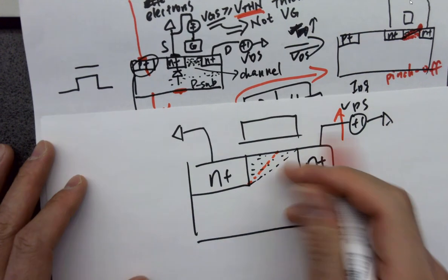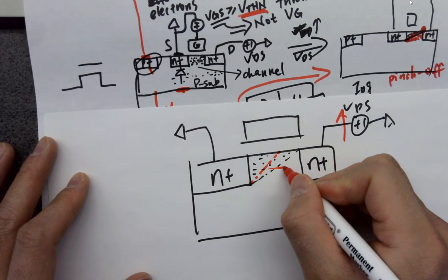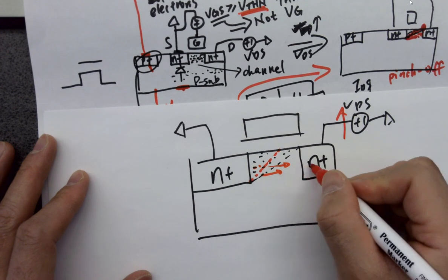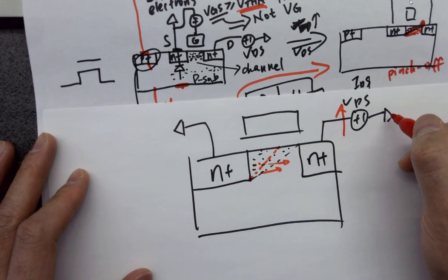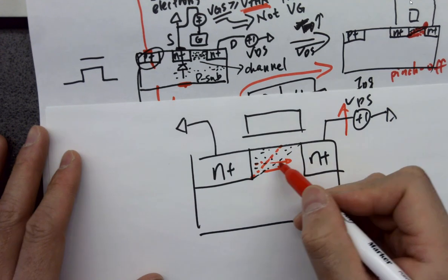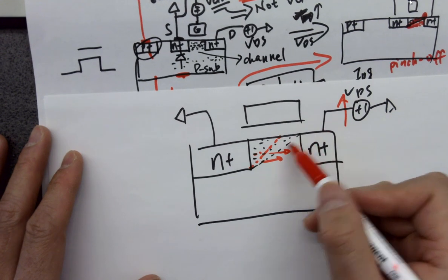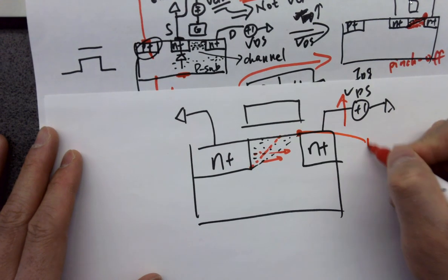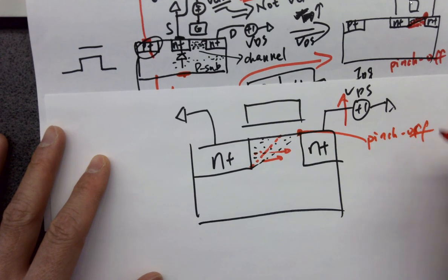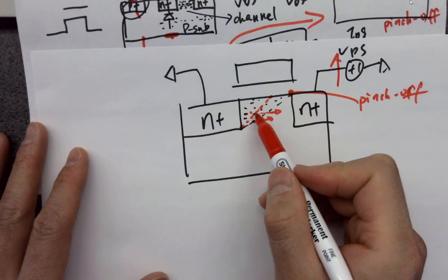The reason for that is because it's a super small area, right? So the electrons will tunnel through. These electrons will go through this area, reach the drain terminal, and go back to the ground. So it's still able to circulate these electrons in the circuit. Still runs current. But after pinch off, when you increase VDS, the current value is not increasing anymore.